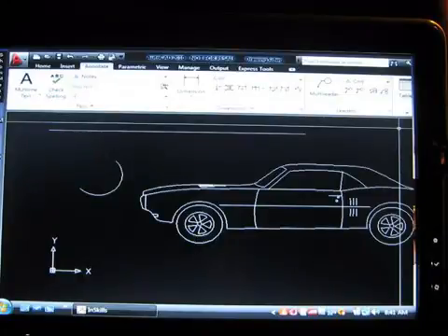One example is the block editor. Blocks are a group of drawing objects that become one object. Blocks allow you to use repetitive objects very quickly. They can't be edited except when you're in the block editor mode. Being in this mode will open up a contextual ribbon tab that will allow you to edit the block. There are other contextual tabs, but I don't want to list all of them now. The list could be confusing. But that's alright. I'll point them out to you as we go along in the process and as they become available to us.